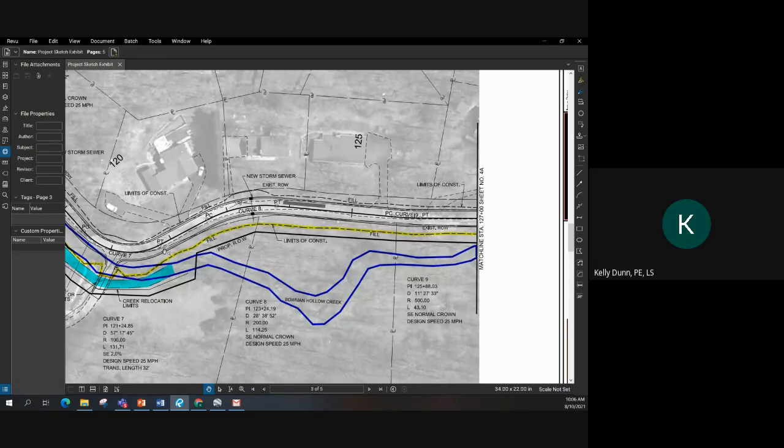Sometimes having a little bit wider lane has other benefits, but one of the other benefits too is you don't have to install so many curb inlets and so much stormwater system improvements to capture the water and keep the spread from spreading so far out into the lane, if that makes sense to you.